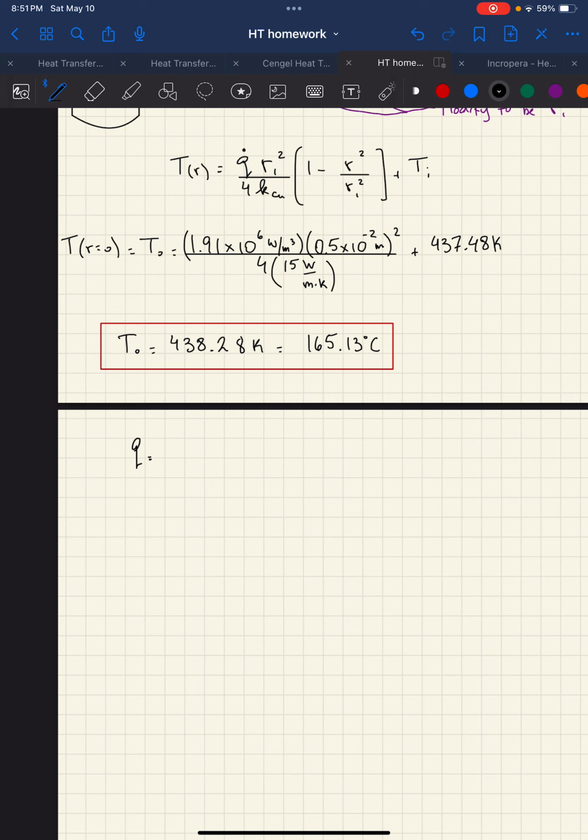It heats up, right? So that energy is basically your heat energy. If you were to calculate the rate at which that energy is dissipated in the power cable, that's your Q, which is watts. Watts is power. So Q is quite literally equal to the electrical power that's dissipated in the power cable.